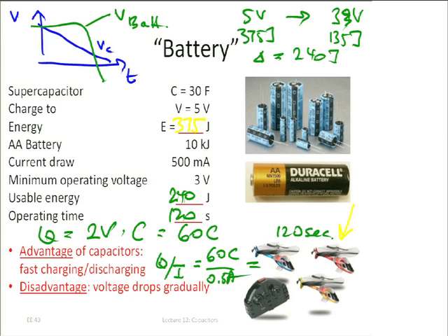I wouldn't want that one, but anyway, one thing that works very well, you worked on it in the first lab, is light, right? Especially solar energy. Solar energy is something really good to scavenge. So getting back to a capacitor, you can load that solar energy little by little, right? You let it trickle into a capacitor, and then when you want to make a measurement, you need maybe a lot more current than is available from the sun, especially at night, right? But then you use the energy of the capacitor, and then you fill it up again when there is light.